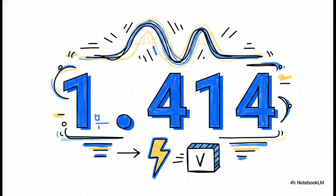Now, the square root of 2 is roughly 1.414, and this single constant number is literally the magic key you need to unlock the whole problem. Whenever you know the soaring, absolute highest peak of an electrical wave, you just divide it by 1.414, and boom, you instantly have your practical, working, effective RMS value.